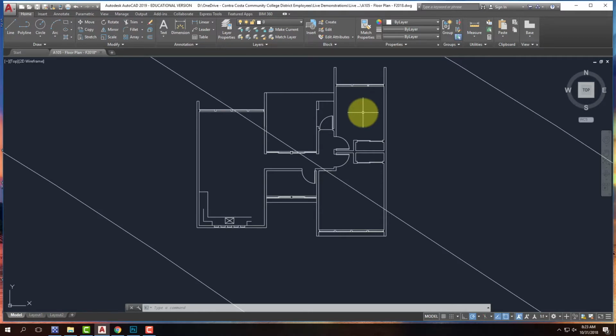If the architect's done and passes the drawings off to, say, an engineer, depending on the engineer, whether it's a structural engineer or a civil engineer, their layers would typically begin with C dash for a civil or S dash for a structural. If you were doing a mechanical engineer, it would be M. So we try to designate layers based on who's working within that context.